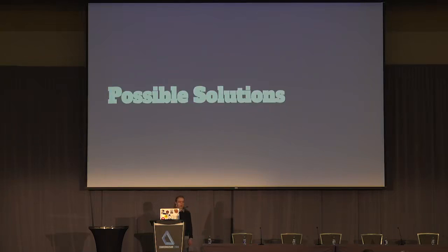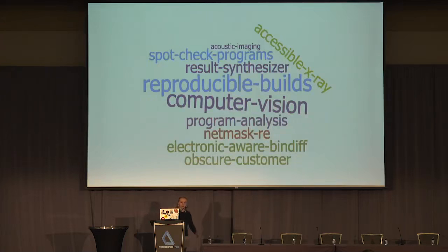All right, so possible solutions. There you go. Computer vision, machine learning. No, I do think that there's more room to be done on automating the reverse engineering process of these IC components as well as the actual board itself. So one thing that I really do want to see is better tooling around lifting netlist off boards, looking at the integrated circuit connects. We need the ability to automatically trace or compare lifted netlists or X-rays between each other.